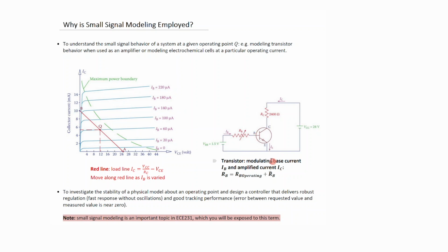All right, so for this particular blue line, what we would do is look at the relationship between the voltage between the collector and emitter, which is the voltage seen along the x-axis, and the collector current, which is the one you're seeing through here, that's flowing into the node at C. If you adjust the voltage, you'll see a change in the current. These show, for a given driving current, that if the collector-emitter voltage goes up, let's say to 32, this would correspond to a current on the order of about 15 milliamps.